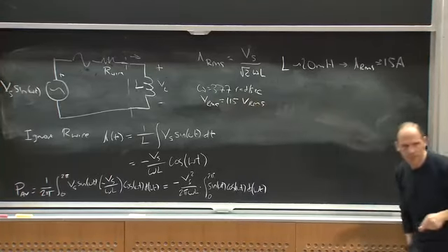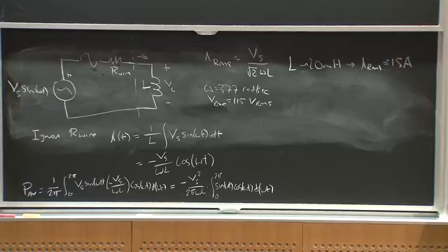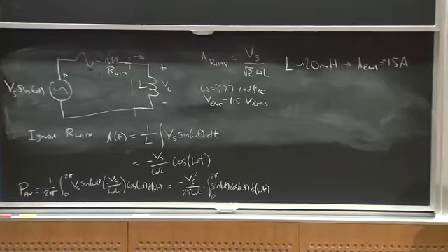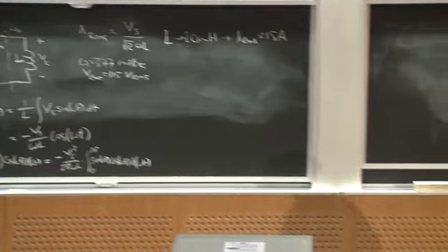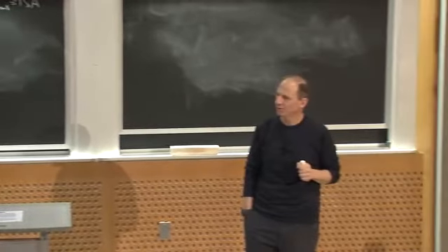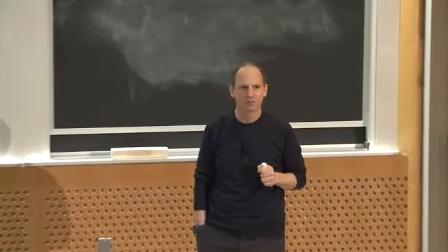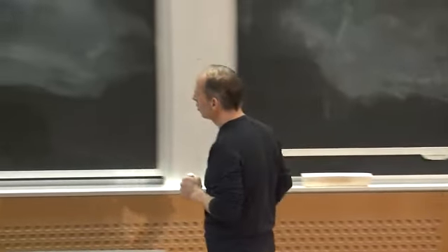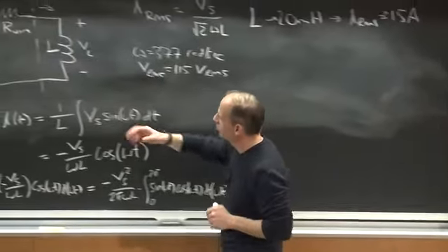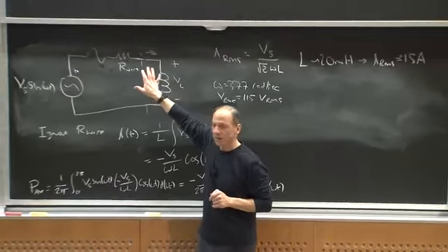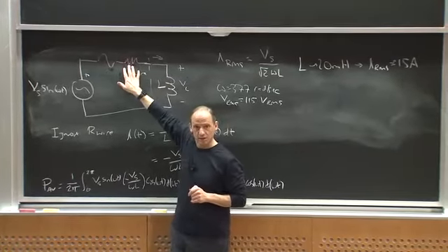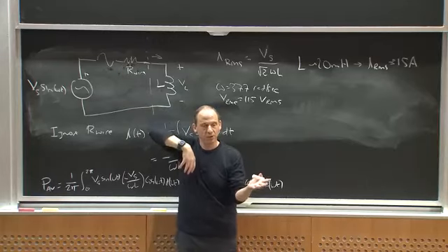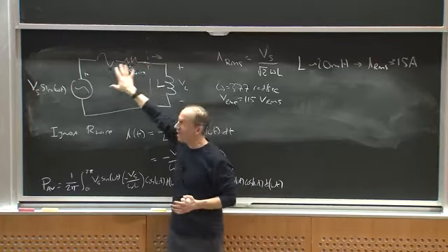Okay? So what does that mean? If I go out and get myself a 21 millihenry inductor and I plug it in, life's good, right? I enjoy the magnetic fields. If I instead brought my 19 millihenry inductor and plugged it in, well, I'm going to lose the breaker and I'm going to be sitting in the dark. Okay? So while the inductor doesn't consume average power, it does draw a mean square current, okay? And it does degrade the ability of me to utilize my source, right?